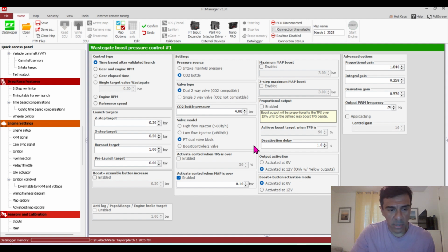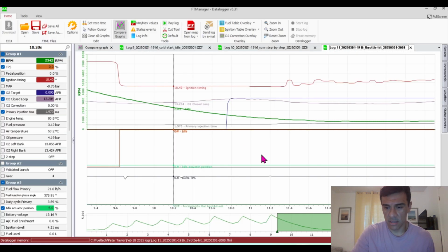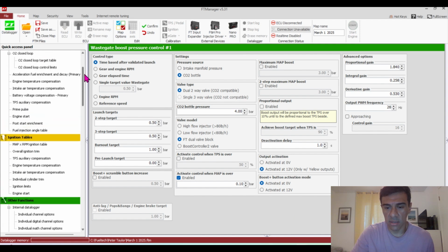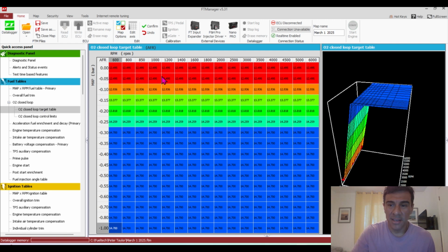Again, you can use the basic setup. A lot of people get away with it, but it is advisable that you should probably do that. And the same thing applies for the boost control. I mean the O2 closed loop. A lot of people rely on it, and unfortunately, in the FuelTech, it can overshoot and undershoot. That's the reality. You need to get your fuel table set up correctly. I mean, the first step in any tuning is for the PID control not to do much work, at least for the fuel side and things where you can control that component. Get all that on target before you rely on anything closed loop. Once the closed loop is turned on, it's just kind of there to clean up minor imperfections, or just in the event that something happens, whether fuel pressure drops or what have you.